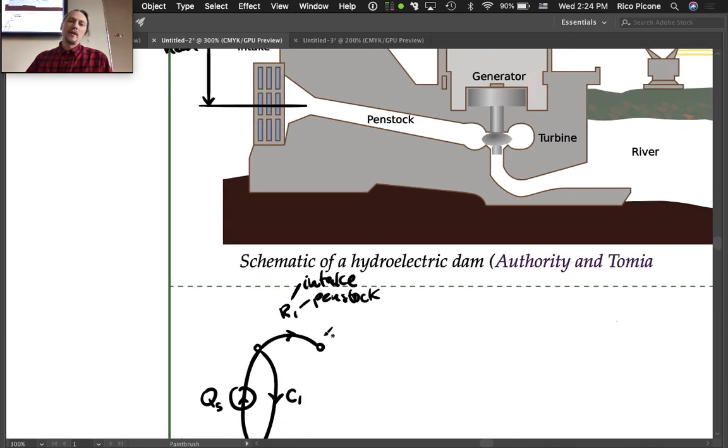So I'll put that element in, and then just to be confusing, instead of using I, I'll use L1. The fluid inertance is often used with the symbol I, but it's an inductance. It's a generalized inductance, I guess you could say. We often will also use L for it, so we kind of switch back and forth between L and I for the inertance. Hopefully that doesn't stress you out.